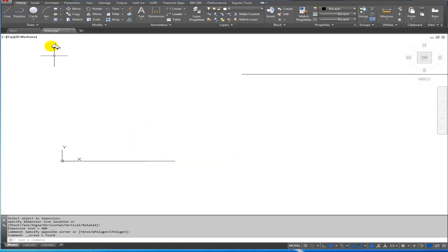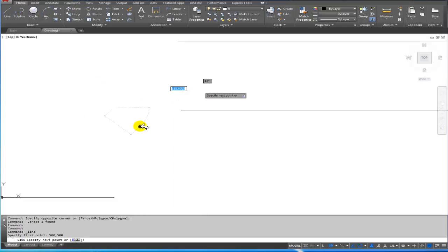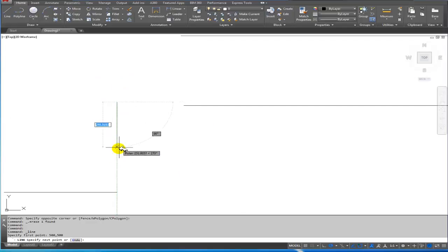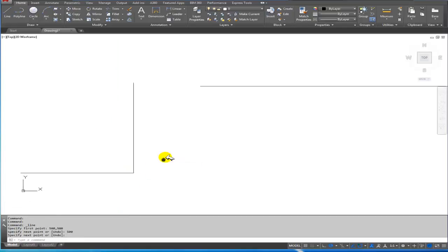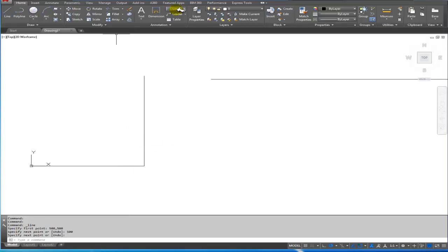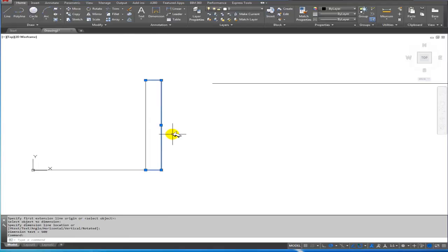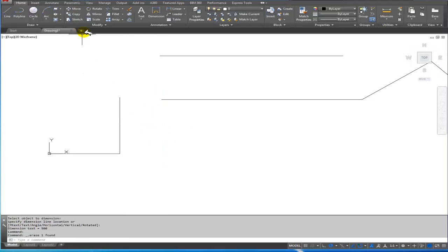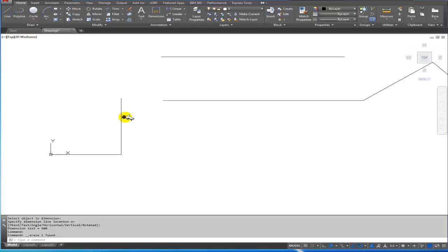All right, so we know how to draw a line. So I could say line starting at 500 for X, for Y 500. So I'm starting at a point 500 by 500, and then I could actually say going this way, using just my cursor, by 500. So I don't have to, so it brings back to that point. So that line is also 500. There you go. That's good. So we know how to draw a line. But I'll come to drawing a line at an angle at a later stage. But for now, let's just look at a simple line.